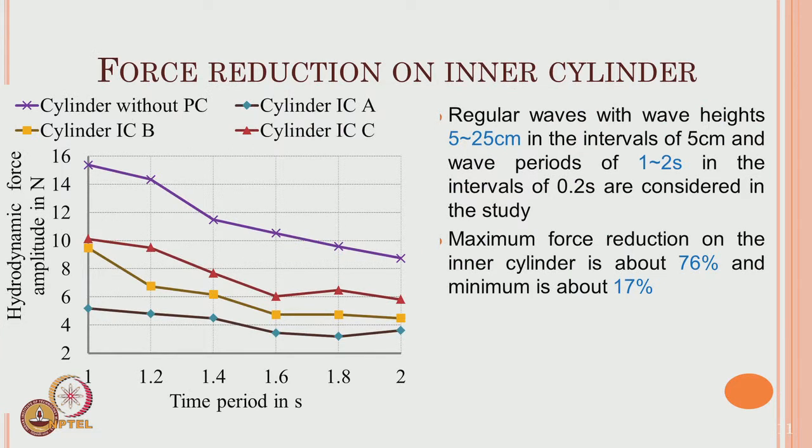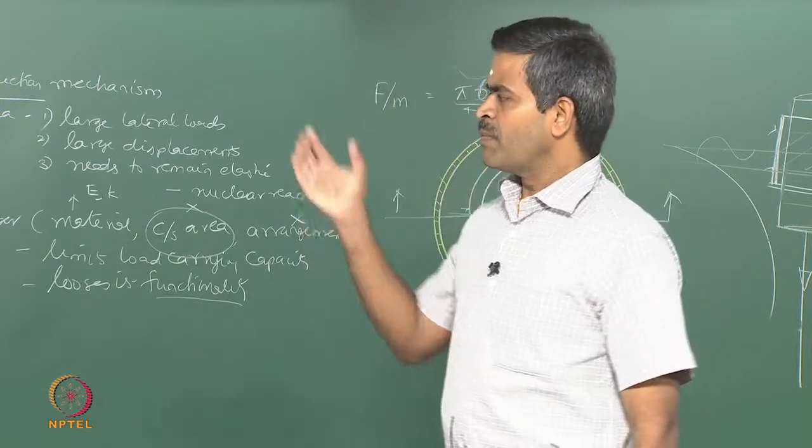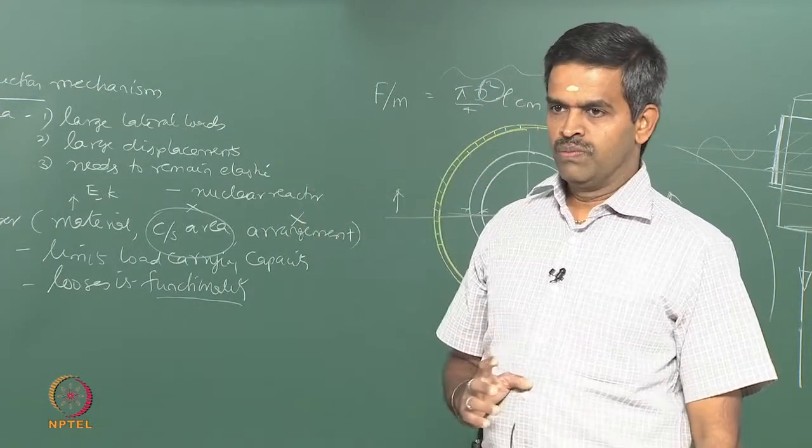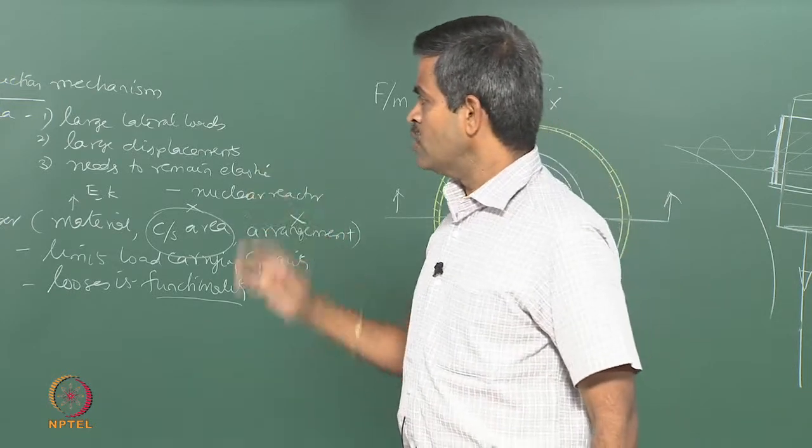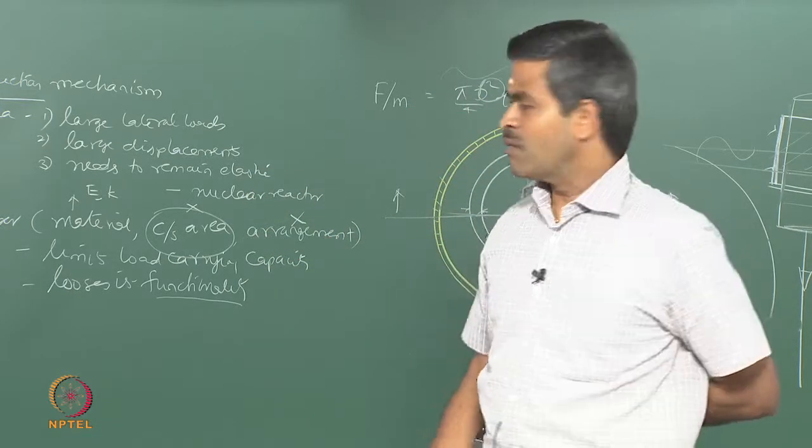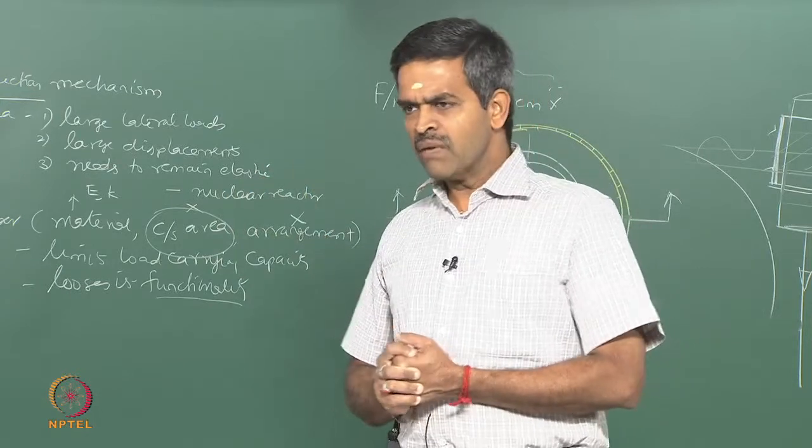You will see that obviously the one which you show here is without any cover. The other 3 are all with cover. You will see there is a significant reduction in the force amplitude measured experimentally, through and through for all the time bands of 2 seconds. When you put a cover, there is a reduction. So, this experiment gave an indication, a verification that yes, whatever people stated in the early literature is true, and we also measured the reduction to be close to about 76% maximum and about 17% minimum. So, you get some reduction in the force.